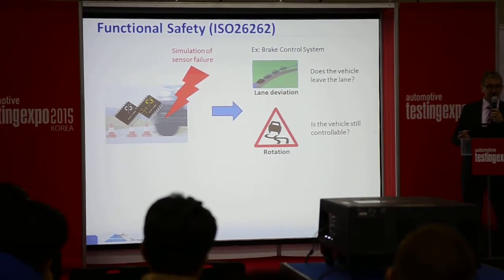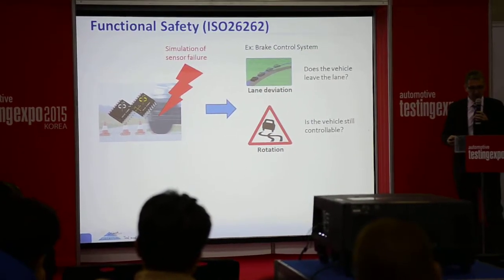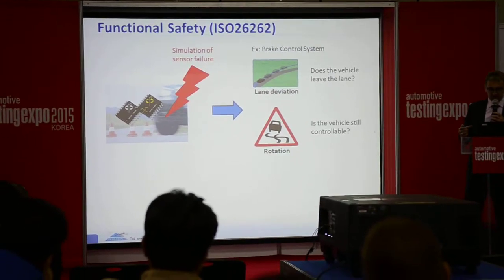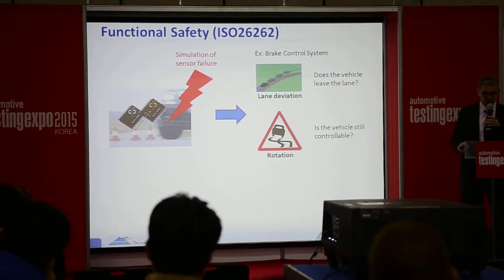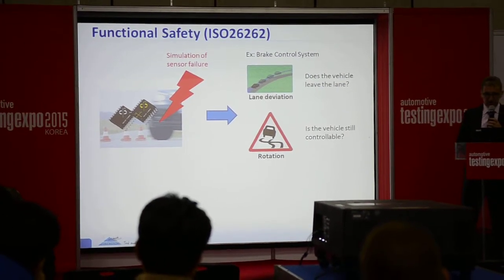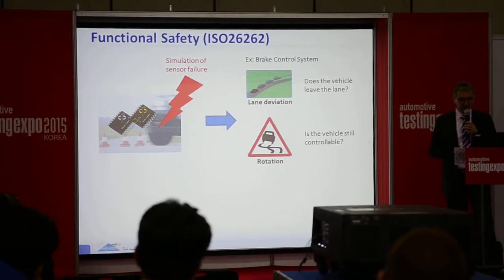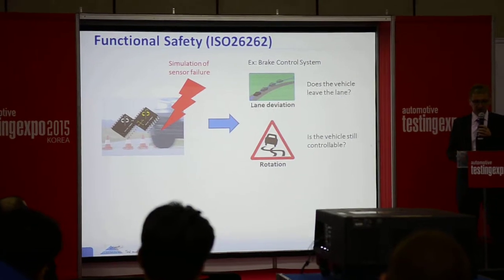Finally, how is this classification to ASIL achieved? It is done according to the severity of the potential hazard, to the frequency of the driving situation, which is also called the exposure, and to the controllability for the driver. With the rising ASIL, also the safety requirements for the corresponding system will increase.